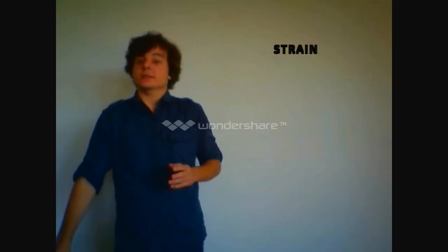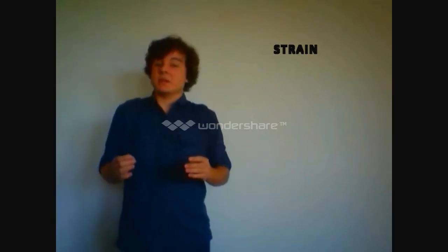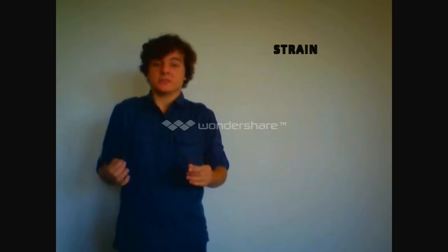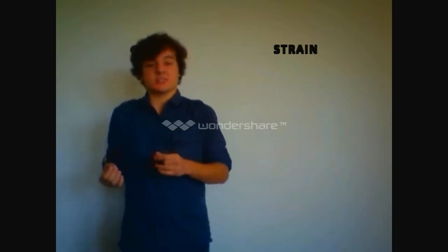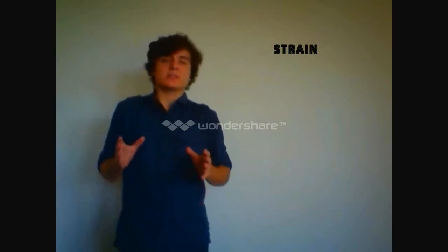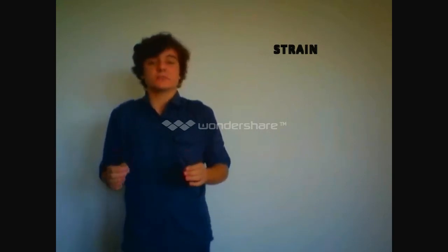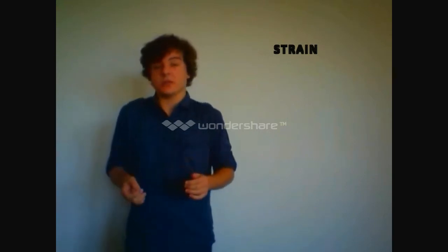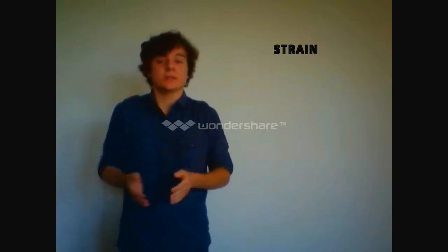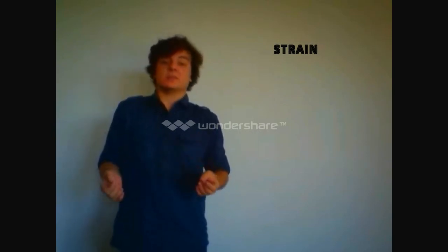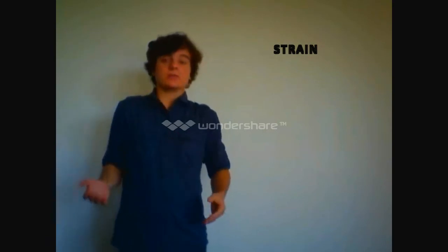Now on to strain. Strain is defined as the amount of deformation an object experiences compared to its original size and shape. For example, if a block 10 centimeters on a side is deformed so that it becomes 9 centimeters long, the strain is 10 take away 9 divided by 10, or 0.1, sometimes expressed in percentage, in this case 10%. Note that strain is dimensionless.